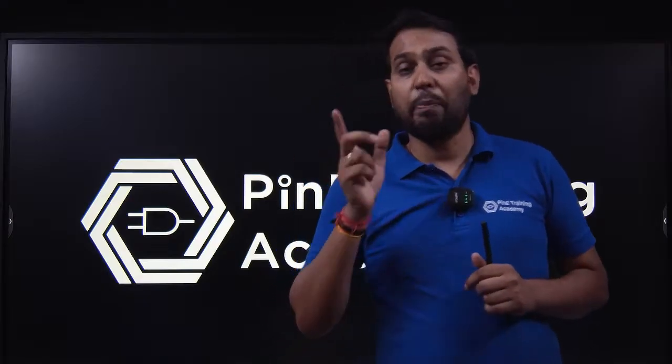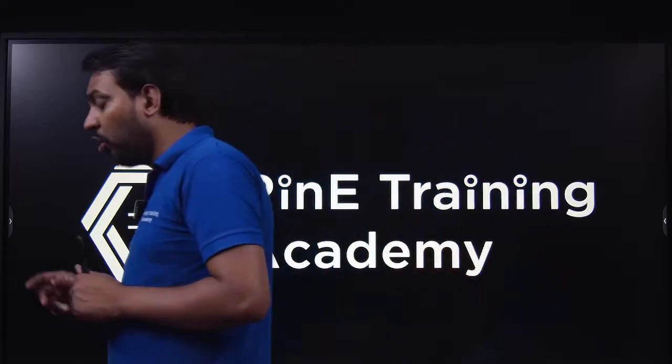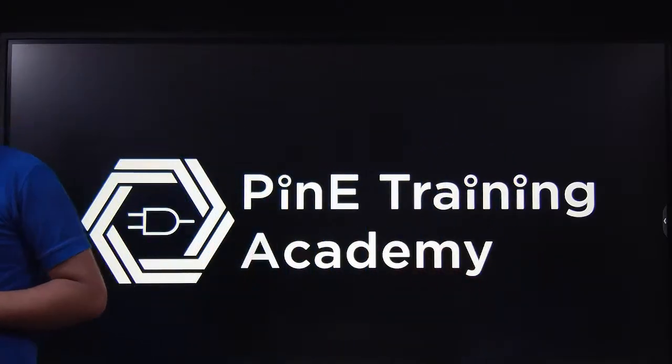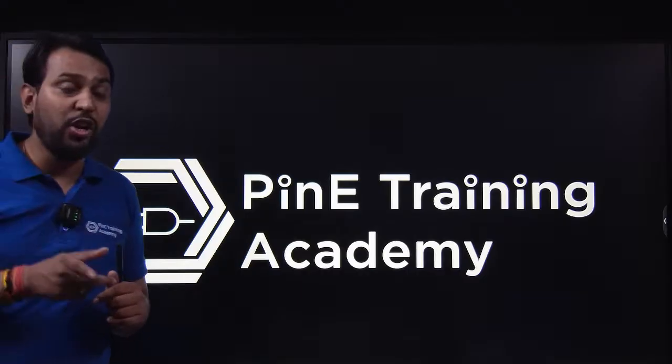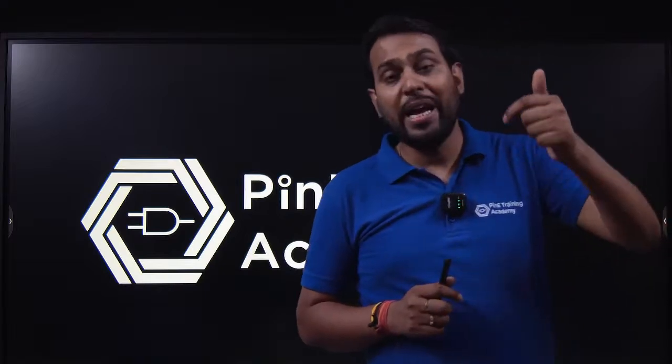If V1 is higher than V2, V1 will be the drain in NMOS and V2 will be the source. For PMOS, the body is N-well and you have a gate, source and drain. If V1 is greater than V2, V1 will be the source and V2 will be the drain. So the higher supply in NMOS becomes the drain, and the higher supply in PMOS becomes the source.